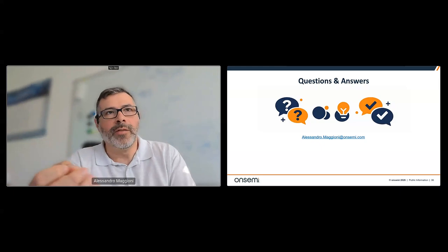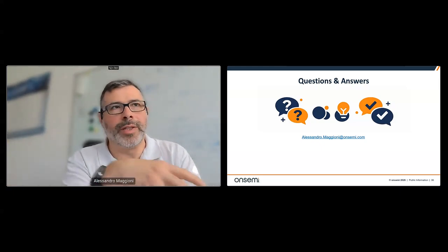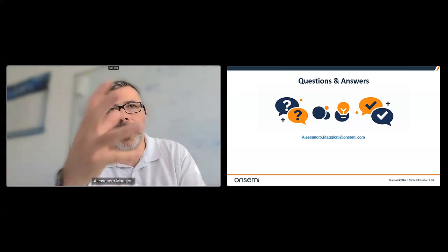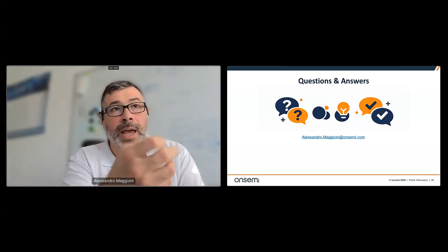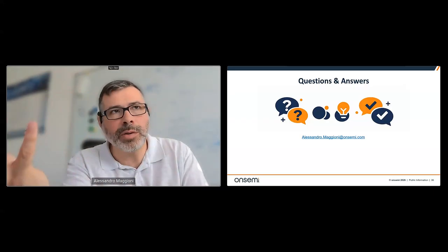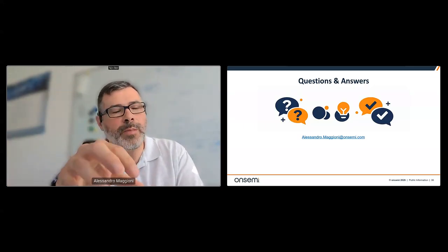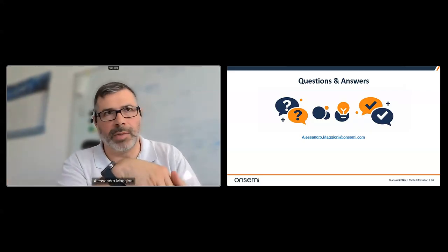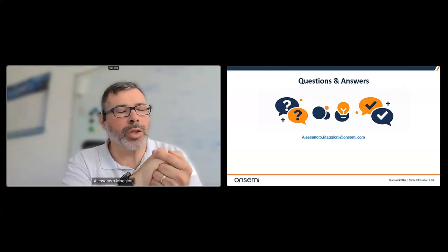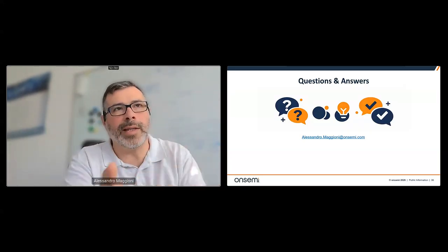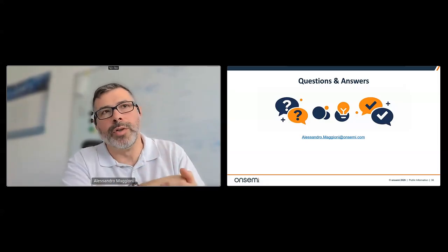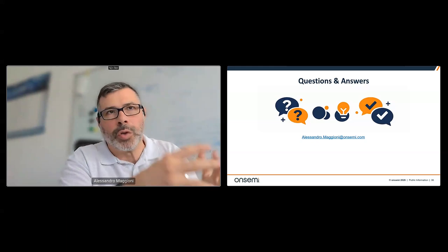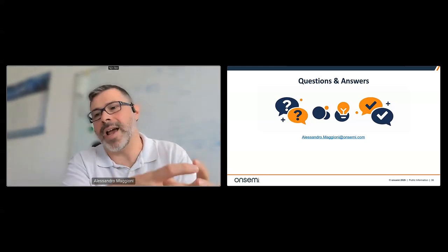For example, we saw the example of the 11-channel front lighting module. That demonstrates how it works. It's an MCU-less, shunt-less board, where the 10BASE-T1S input feeds the RCP device directly. It has an EEPROM on board for full configuration. The result is you have fewer components, no node-level software, and a reduced bill of materials and board area.